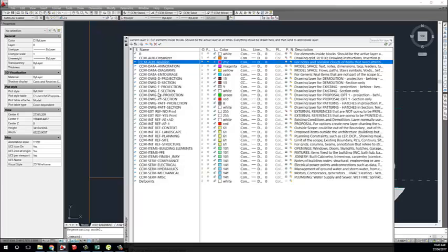For more information on that, you can just read the layers type. You have the drawing type just to draw. The external reference for images or another drawings from other people, and then the internal reference. So we have the existing demolition, proposed, the context, so everything outside the boundary, landscape, everything between the building and the boundary, planning for planning controls, maximum height, maximum footprint, things like that. Site, which is mainly the boundary and the areas of the boundary. That's key, it's a fixed block, all of them.